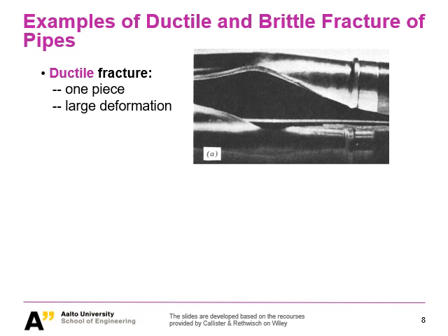So as you can see, the first example here is a ductile fracture of a pipe. And just a few important features for you to see. First of all, this pipe is separated, of course. You can see the cracks developed, but what's important is the whole pipe is still one piece.